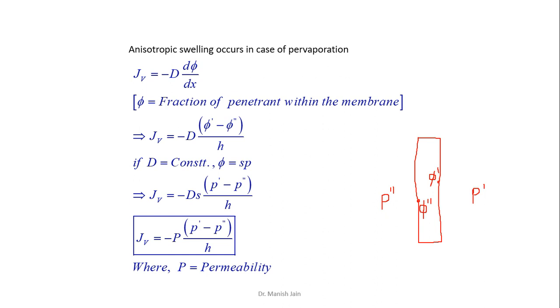So as I told you, in the pervaporation process, the transport process can be defined by the solution diffusion model, where the feed species is first selectively absorbed at the surface of the membrane, then diffuses across the membrane, then dissolves at the permeate side in the vapor phase.